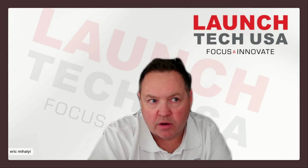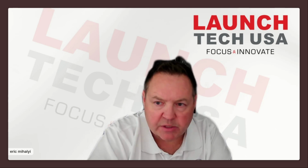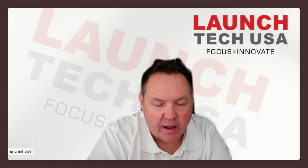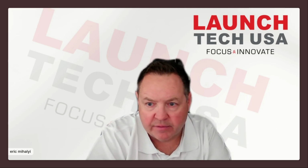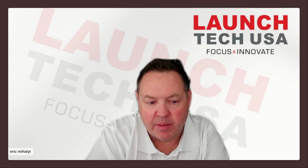Nowadays when I work on a car, I pretty much start with service information before I actually start working on the car. Once I get that code or whatever is in the system, my next step is service information, whether it's reading the description and operation of the system, like an EVAP system. Sometimes things are different than maybe what you're used to. Maybe the vent valve is normally closed or normally open. You've got to find that out. If you just assume because most of the vehicles are this way and this one happens to be different than that, you could make an error.